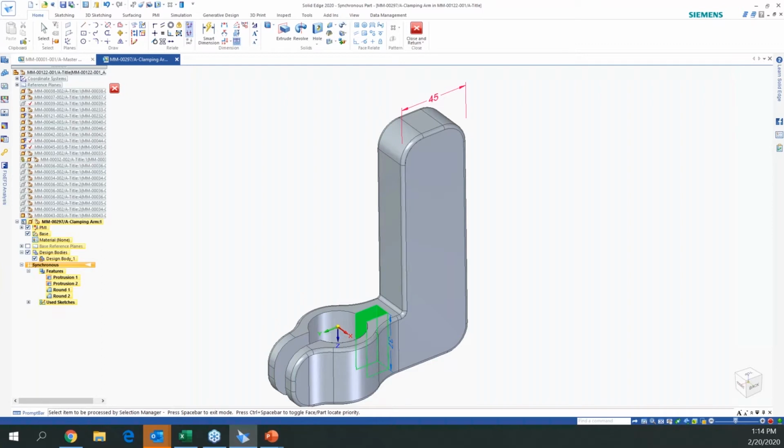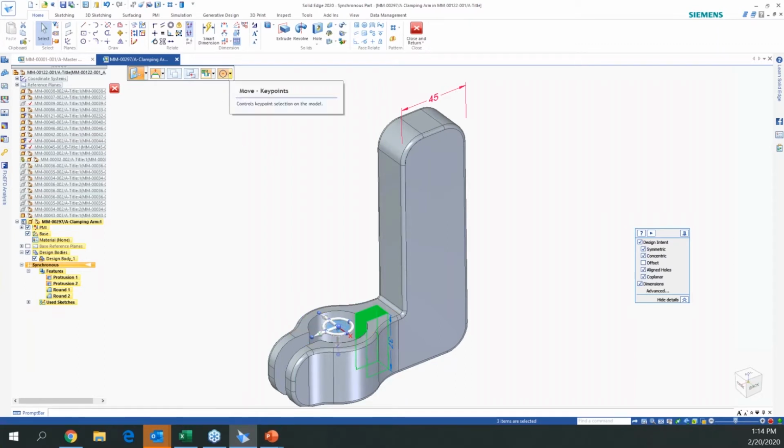Okay, I hit shift space bar one more time. It gives me my steering wheel. I can move that over. Now I want to select the midpoint here, because I want to take that steering wheel and put it over here on this midpoint. So if I hold down my shift key, grab that steering wheel, because I want to hold that, and select the middle line there. See, there's my middle point.